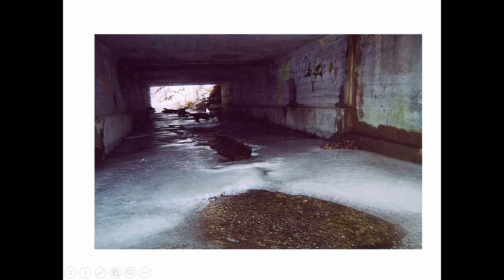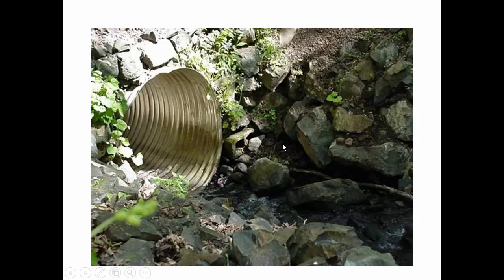In other cases, you can see that there's been some scour under the culvert, some hydraulic scour, and when the flow rate gets really high, there's a lot of energy that's being exerted on the bottom of the channel. And the scour can, if there's fissures in the rocks, or if you have a blocky or aggregate bottom, wash all of that out during high flow conditions and potentially undermine the strength of the foundation.